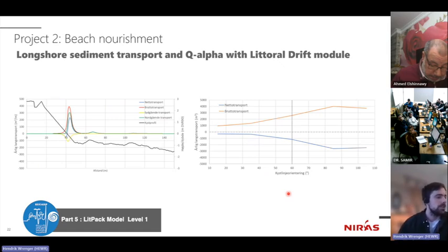It will be transported along the beach and lost eventually to outside the project area. Sometimes, if the difference between the coastal orientation and the equilibrium orientation is small, we also discussed that I think already, then with small structures like groins, I can change the orientation, because the sand is accumulating on the one side, maybe by 10 degrees or something like that.